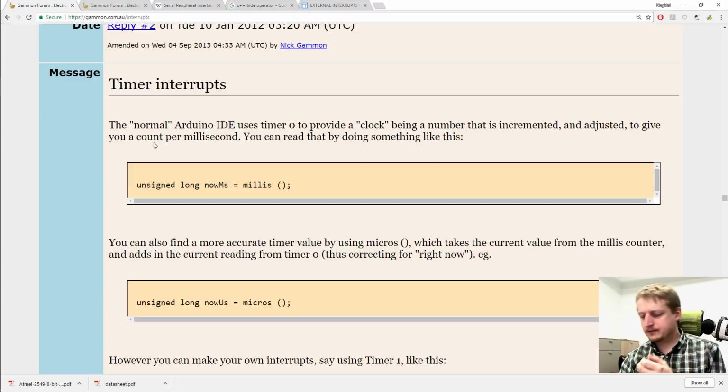The problem here is that normally you use interrupts only on pins. But here we want a special interrupt, namely by timer. I want the program to do nothing except, once a second, see what happened in the last second: how many propeller blade passes it registered, and then calculate the RPM from it.